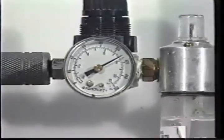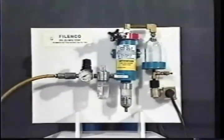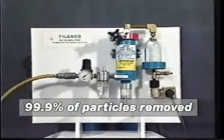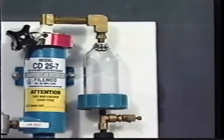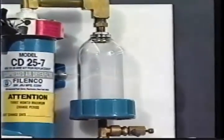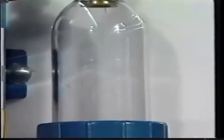Air then passes through the desiccant bag where it is filtered and dried, then through the final filter, where laser tests have shown that more than 99.9% of particles 1 micron or above are removed. In this test model, the air is then discharged into an inverted polycarbonate bowl. As you can see, there is no condensate here, even after the air has expanded and cooled.